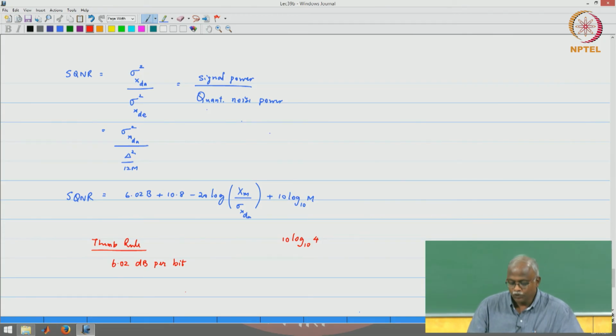Which means that what I can achieve with 1 additional bit, I can achieve with oversampling by a factor of 4. Of course, if you already have a 16-bit quantizer and you now say I want 18 bits of precision, it is possible, because you can do oversampling by a factor of 8, and then 4 times 4 is 16, a factor of 16, and you will get the required result.